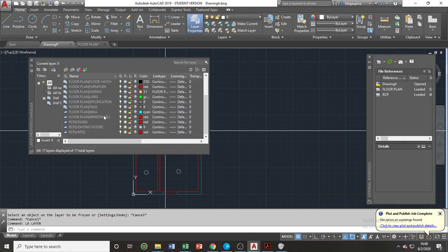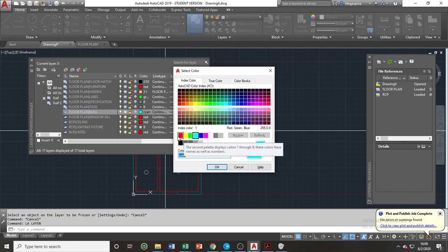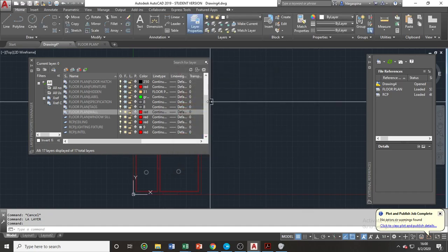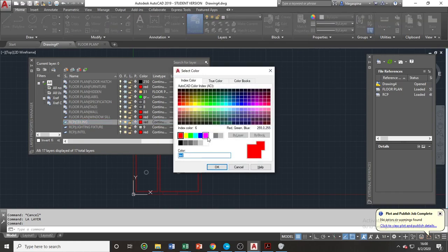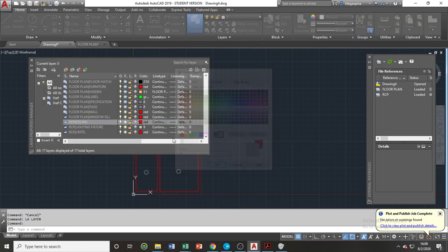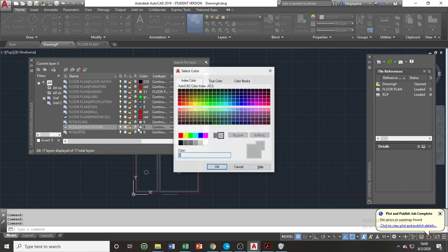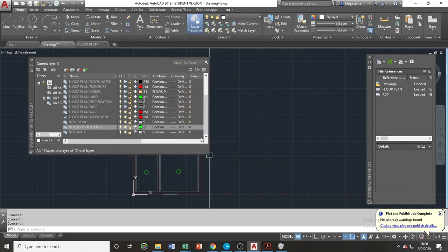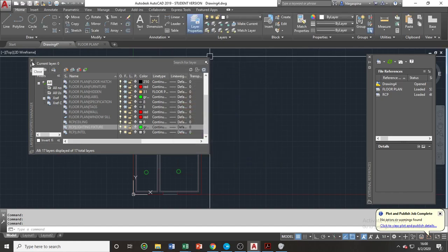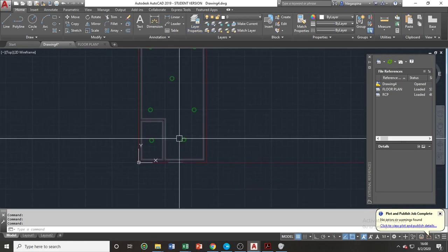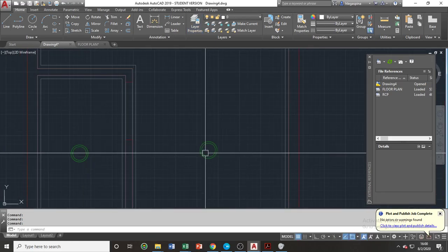We'll edit our layers and edit the line weights of our walls, in which the lighting should be well emphasized in our design. The walls, as well as our ceiling, should be presented in a lighter line weight. For the lighting fixture, this must be well emphasized, so we can use a thicker line weight for our lighting fixture.